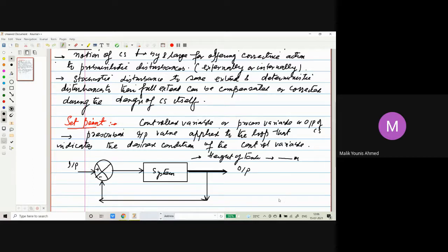A signal will be given to the control system that, let us say, this is your prescribed value, that you have to be within this range, 2.5 meters. This is your prescribed point. So that prescribed value is given to this complete loop, so that it will keep check of this height of the tank, at what time my ball valve or my linkage mechanism will come into operation.